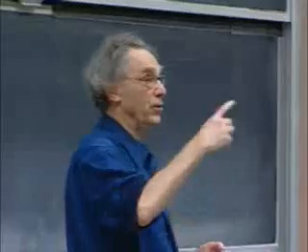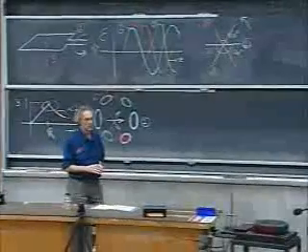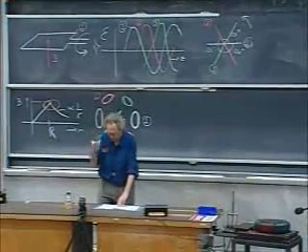Now, if you have an eddy current going around and you have a magnetic field, then the magnetic field and the eddy current will cause a torque on the current. In a similar way, when we discussed earlier the idea of a motor that you were going to build, there was a magnetic field and there was a current, and that caused a torque. In the same way, you get a torque on the eddy current. And so it starts to torque up this conducting sphere. And all the time there will be eddy currents because the magnetic field keeps going around. And so you're going to get a torque which will always be in the same direction, and this conducting object will now start to rotate, and we call that an induction motor.